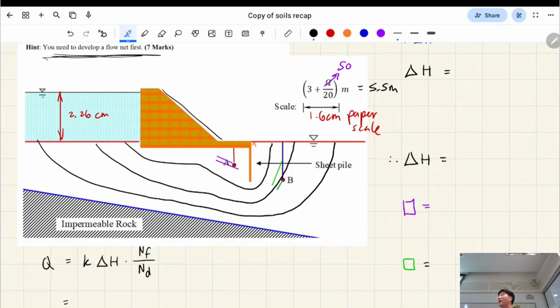I know it just looks like I drew some random lines, which is what I did. But the idea of it is that we try to think about equal spacing, to the best of your ability. I didn't draw it perfectly here, but you want these spaces to be roughly the same when you're drawing your flow lines.